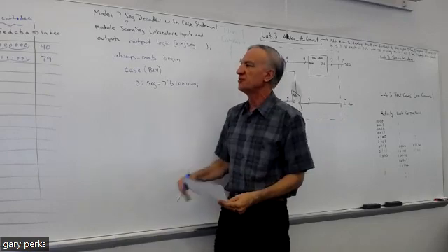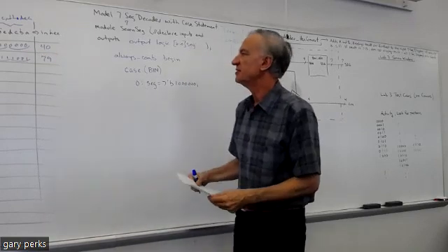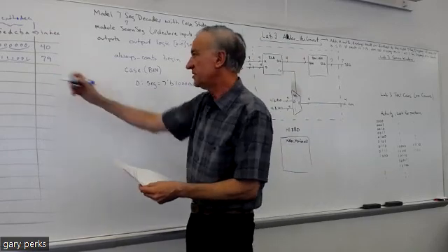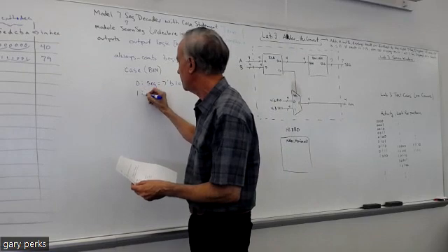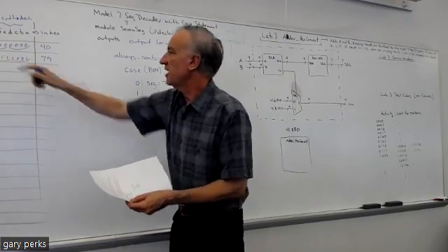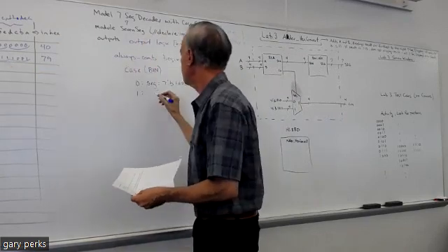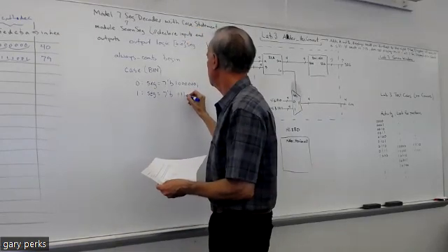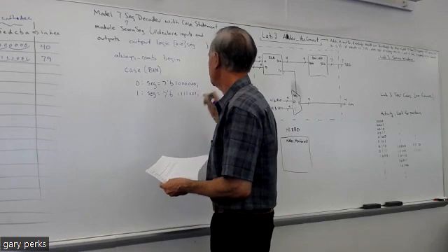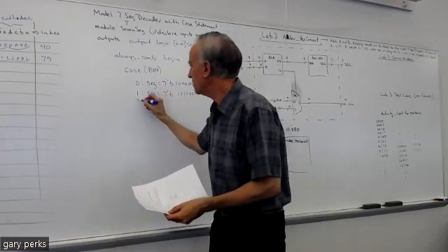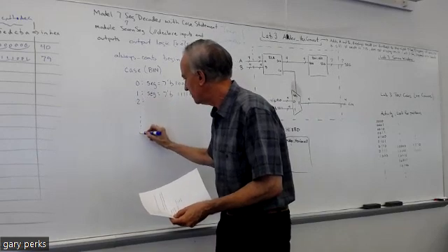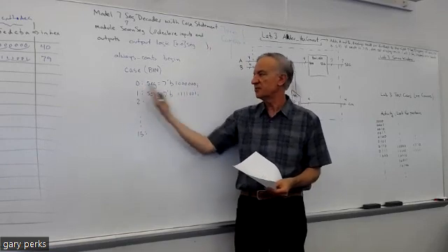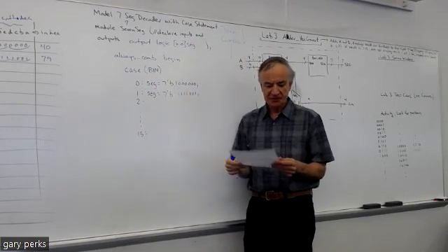But anyway, you can just list out the bits. In fact, maybe from a learning point of view, it's good to list it out as bits, just so it drives home that each cathode has a bit value. Then you just take what you have on the truth table and translate it into this case statement. So, for case 1, which is this row here, we want seg equal to 7 tick mark B 1 1 1 1 0 0 1 semicolon. And you just do that for the whole truth table. You have to go 2, all the way down to 15. These are in base 10; for the options, you just put the base 10 number.